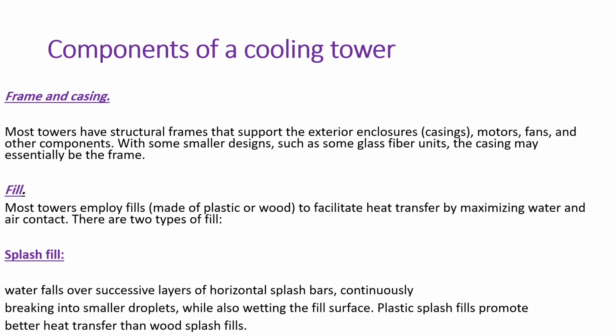Then fill. The main role of fill is to increase the contact area between air and water, because if we have high contact between air and water, the cooling process will happen efficiently. And we have two types of fill: splash fill as well as film fill. Splash fill is used for dirty water, and film fill is used for clean water.